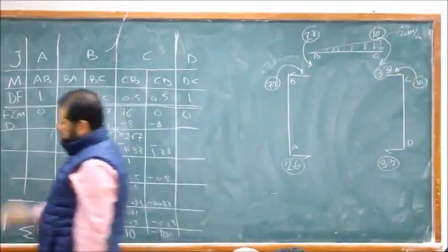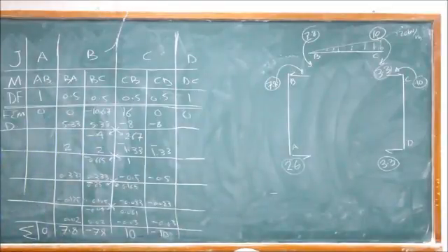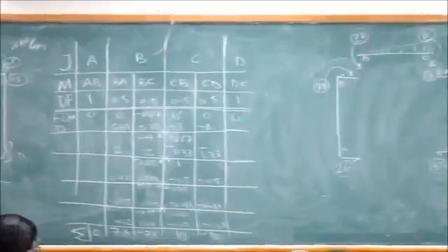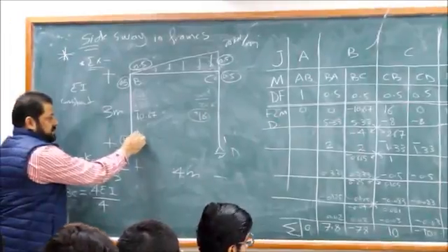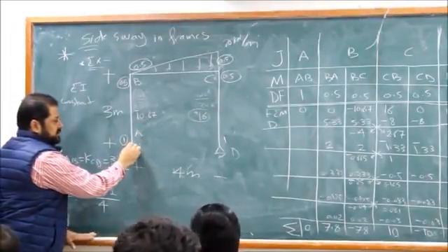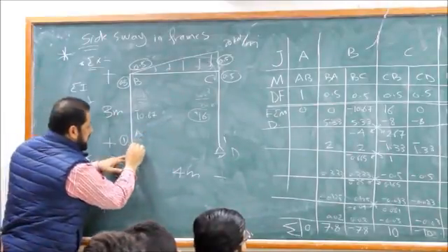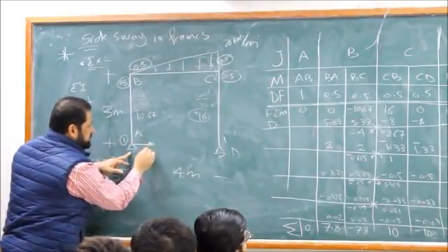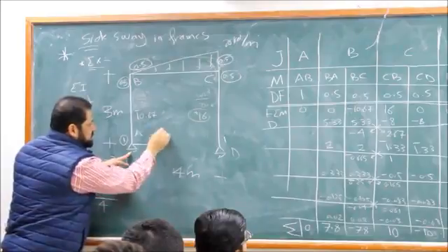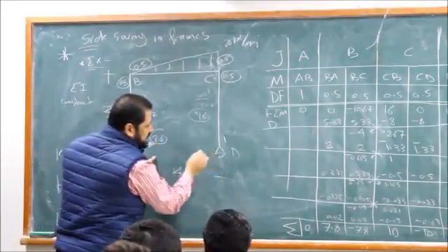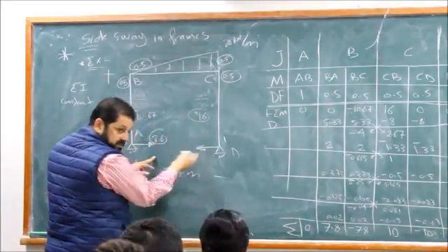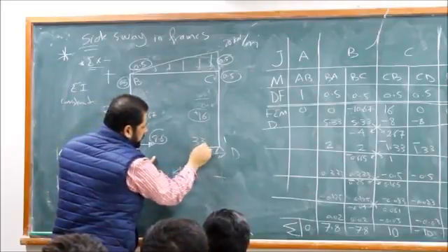So what's the shear at A? It is the reaction at A, right? The reaction in its direction. So we have 2.6. How much is AX? 2.6. So AX is 2.6. And how much is DX? This way, right? 3.3.